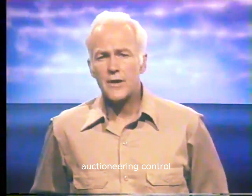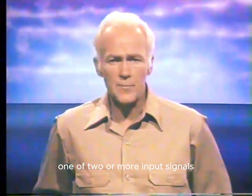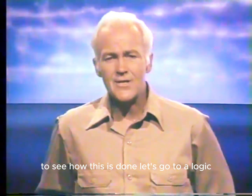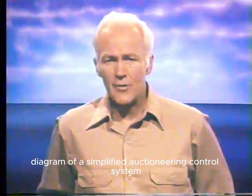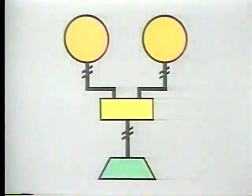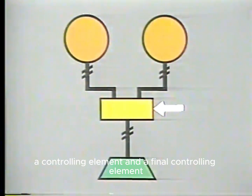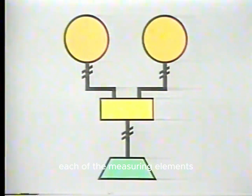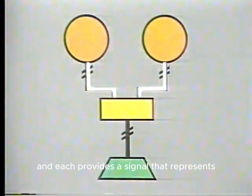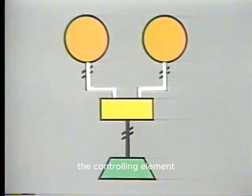Briefly, auctioneering control allows a control system to respond to one of two or more input signals. To see how this is done, let's go to a logic diagram of a simplified auctioneering control system. In this system, there are two measuring elements, a controlling element and a final controlling element. Each of the measuring elements monitors a process variable, and each provides a signal that represents the value of the monitored variable to the controlling element.